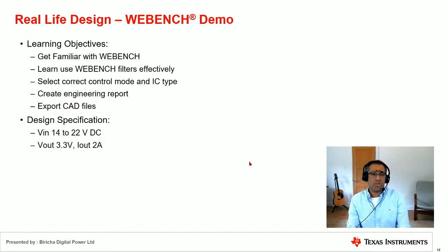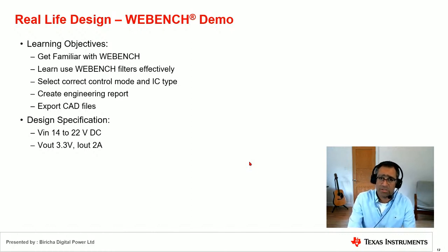The design specification is 14 to 22 volts DC for the input, and 3.3 volts and 2 amps for the output. This is actually the default specification for WEBENCH. So when you open that, this is exactly what you'll see.